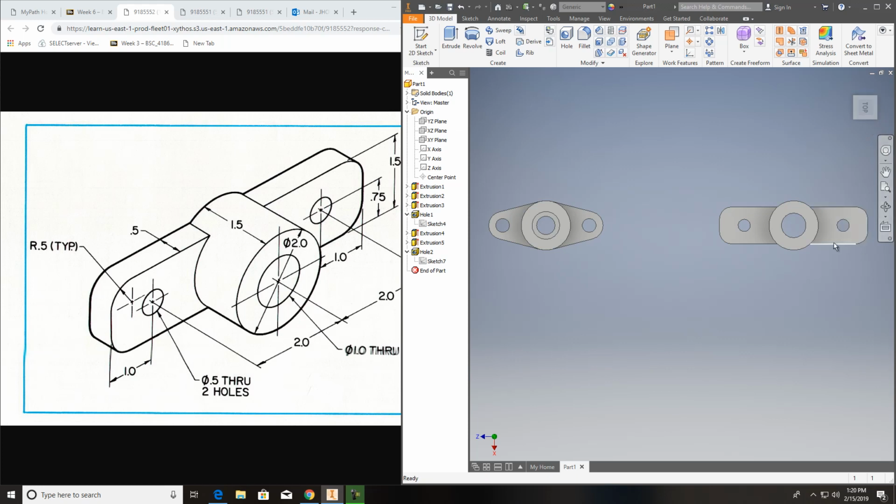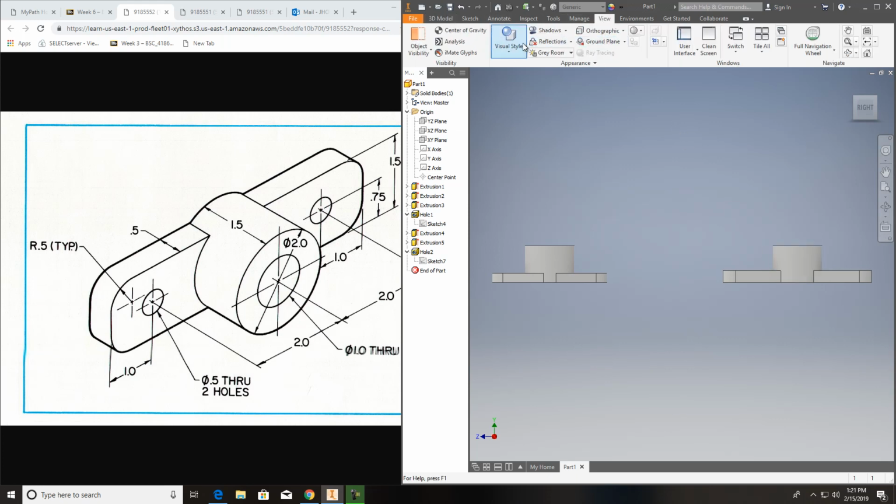And you see how this is not coming all the way out to the quadrants, or it's not being tangent, it's just intersecting right into it. When we turn these around, you can see these. And even if I go up here and do my view and go into visual styles and do realistic, you can still see those lines where that intersects in, where over here when it tangents in you cannot. And you'll just have the lines coming and stopping like right there and there, as opposed to this. And you can see them on the top view as well.